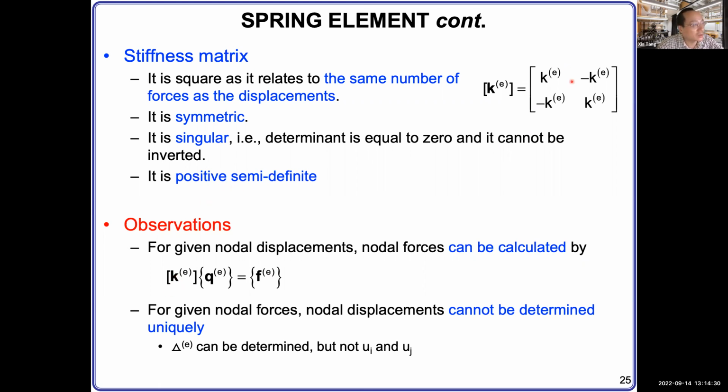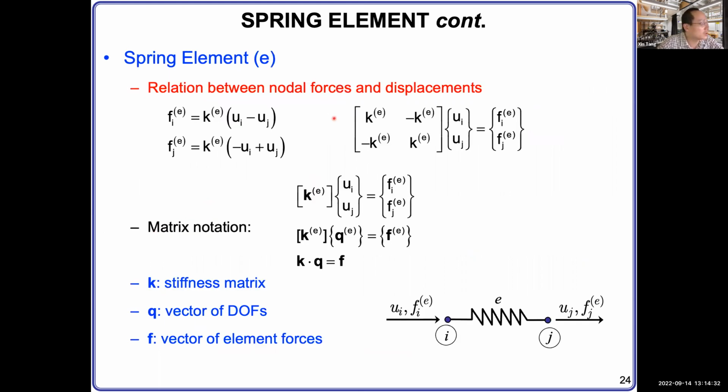These 2 equations are not independent, because if you add a minus sign to one and add the other equation, they equal 0. They are dependent on each other because they come from the same spring. The force is in equilibrium. If you have more springs connected together, then the matrix will not be singular, and you can get a unique solution.